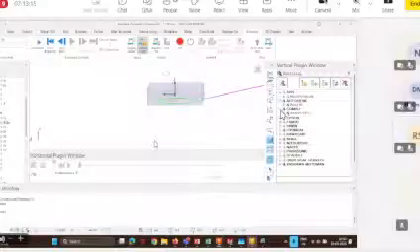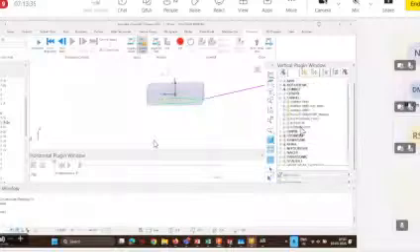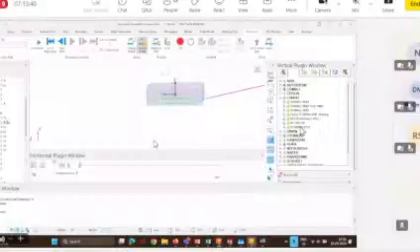For most robots, it lies at the intersection of the J1 axis and J2 axis. Similarly, there are certain robots like ABB where the origin lies at the base, at the intersection between the base and the J1 axis. So whatever robot you have, according to that world frame, you can put the part over here in the cell position.